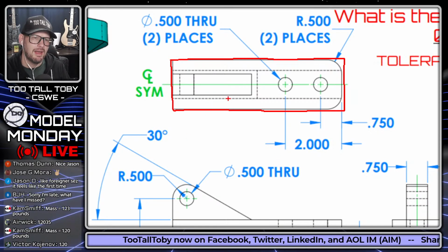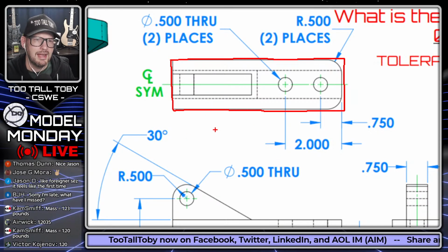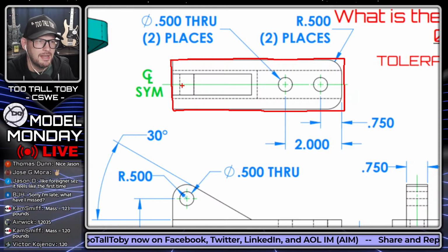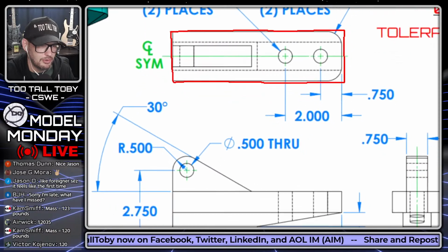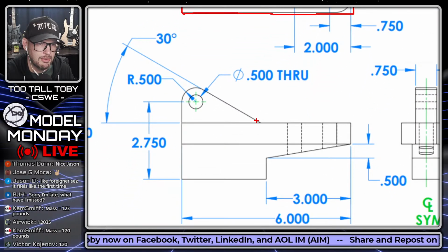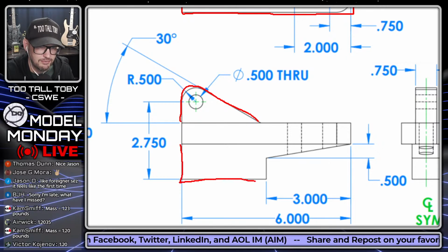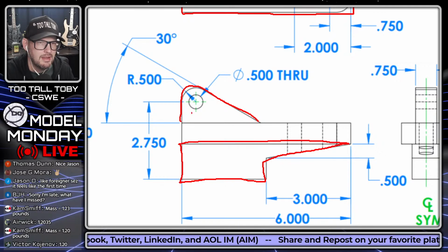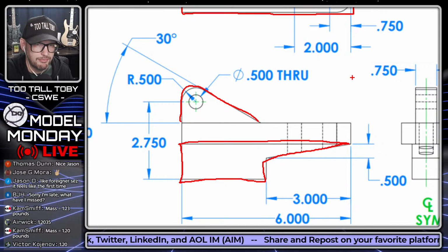Now, why am I doing that? Why am I choosing that plane? Well, it captures the biggest footprint of the design, and it gives me a nice foundation to work off of when I start creating some of the other features. Some of those other features might be this fin here that's sticking up off the top, or this region down here that's sticking down off the bottom. I just think they're going to be easier to create if I create that top geometry first.